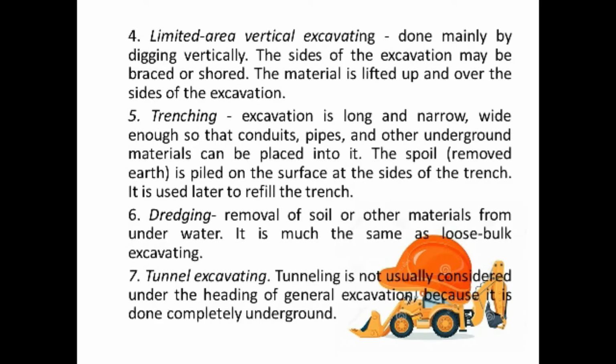Next, we have limited area vertical excavating, which is done mainly by digging vertically. The sides of the excavation may be braced or shored, or simply supported. The material is lifted up and over the sides of the excavation. An example of limited area vertical excavating is digging for a basement.